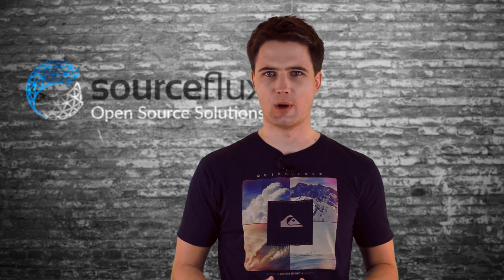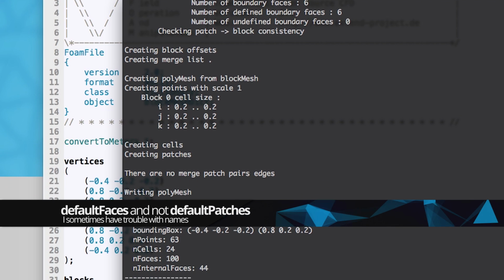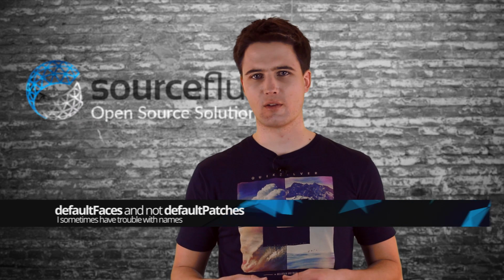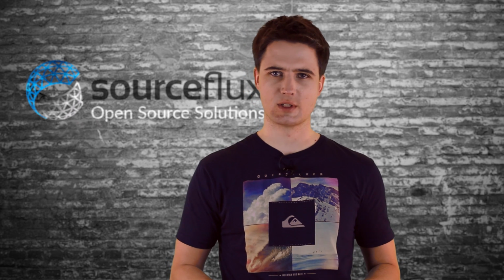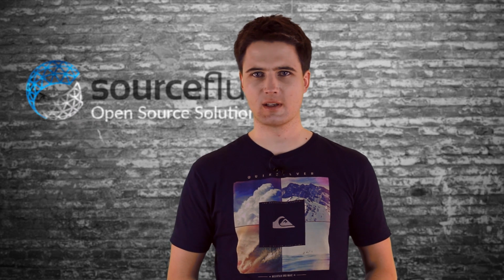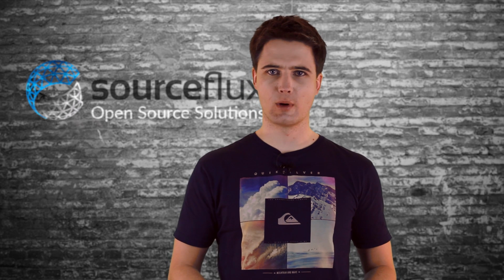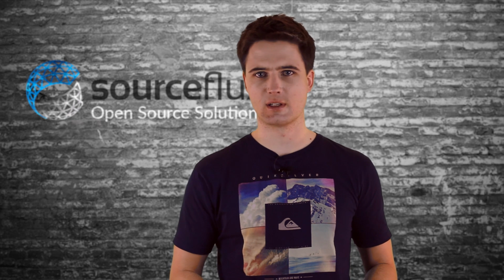What happens when we are executing blockMesh is that blockMesh will automatically assign all those boundaries that are undefined to the patch that's called defaultPatches. So we can later address all of them using the defaultPatches name, and we can proceed with the snappyHexMesh tutorial right now. After these editing steps, please save and close the blockMeshDict in your editor, switch back to your terminal and execute blockMesh. This will create the mesh that is defined by blockMesh and save it in constant/polyMesh.